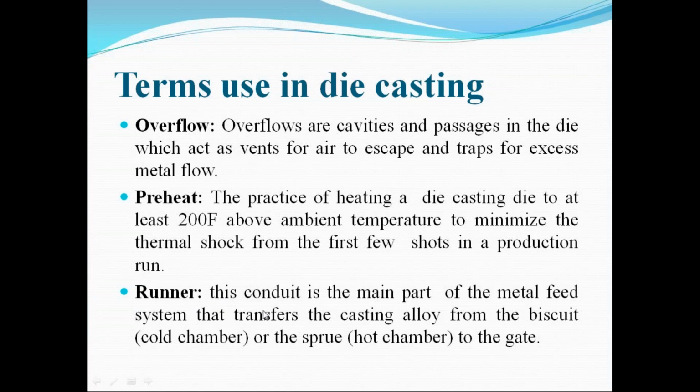Next one, runner. This conduit is the main part of the metal feed system that transfers the casting alloy from the biscuit or the sprue to the gate. So this is the runner. This channel from the biscuit to the gate, this conduit, is called the runner.